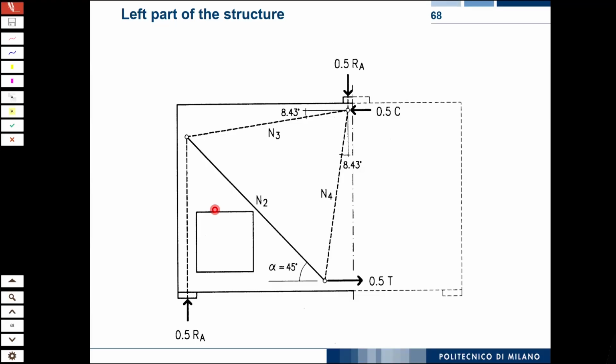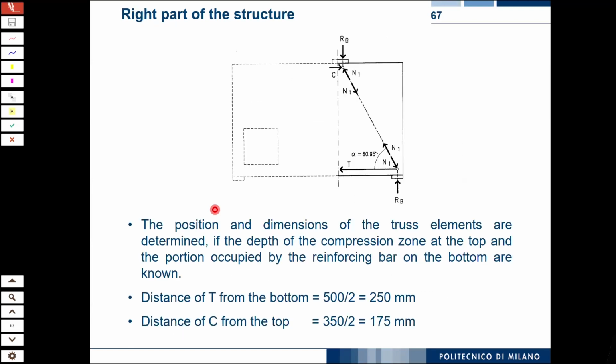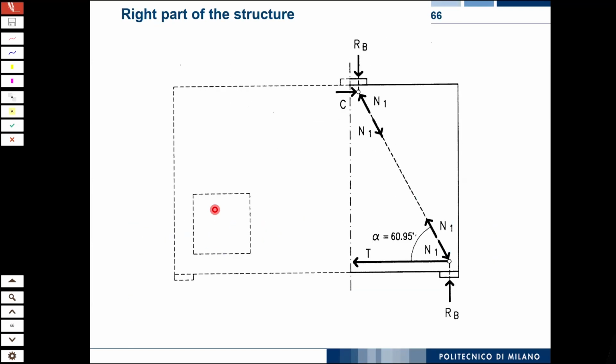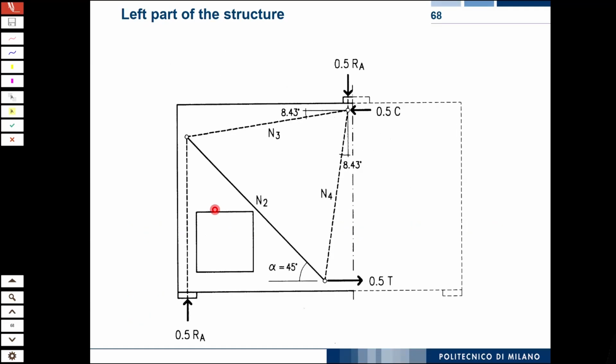So if you have 45 degrees and you align this inclined line straight, you will find this intersection point because you know this position here. That position here is exactly this. It's the same force which has to go from one side to the other. You find these 2 points and you symmetrically locate your other struts. Well, half of R will be assigned to another mechanism. I will show it later.